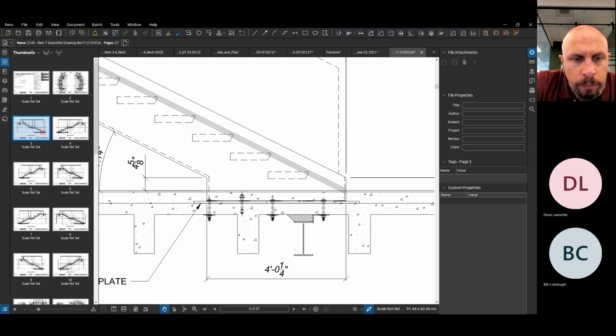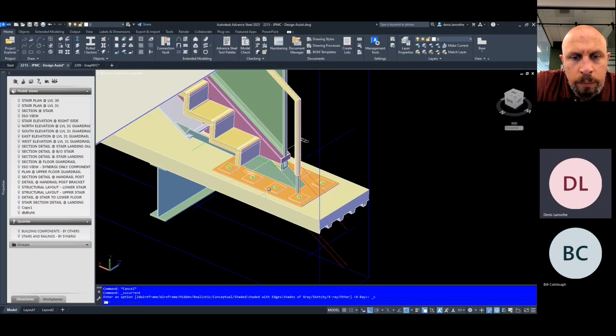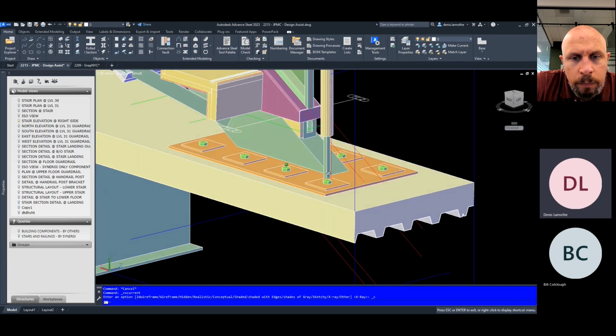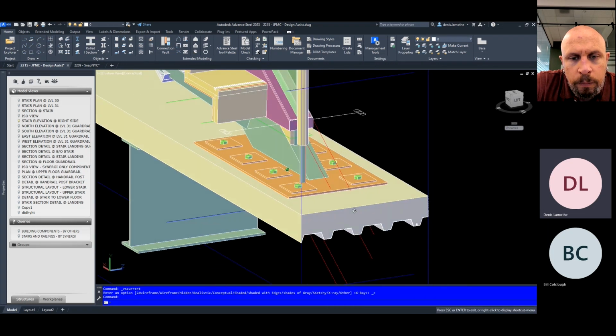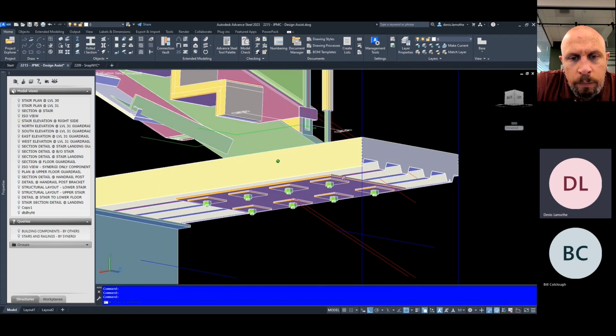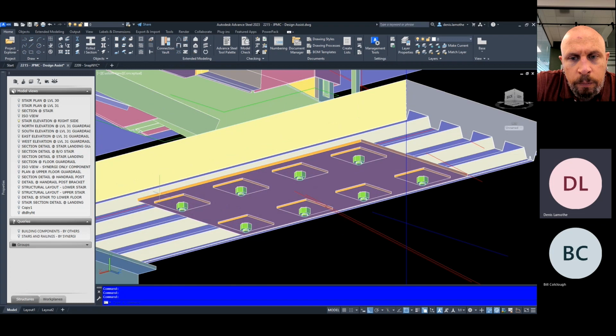And that leads me to this other project that I'm currently modeling right now, JPMC, where we had something similar, although that's just recently been changed from a design meeting we had this morning. But again, the initial idea was to have a base plate, and then we could through bolt the concrete and decking, and then provide a large oversized plate on the underside.